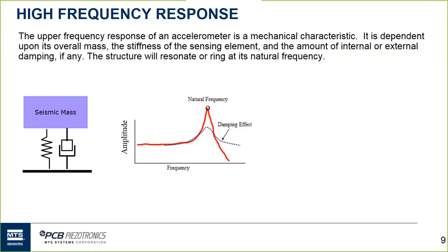And that filter, whether it be low pass, two-pole, single pole, will tend to mitigate that dynamic influence in the measurand by mitigating that high frequency response, providing a better or broader band of measurand with regard to frequency.